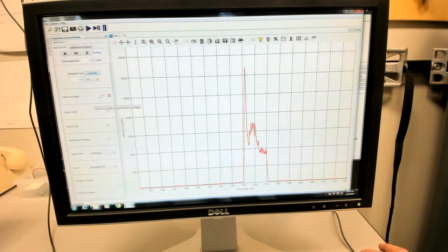The second thing I can do is signal average. If I change this number to 10, then it will show us the continuous running average of the last 10 spectra. It's very useful. The next is called boxcar width. This allows boxcar averaging, which is a kind of smoothing.